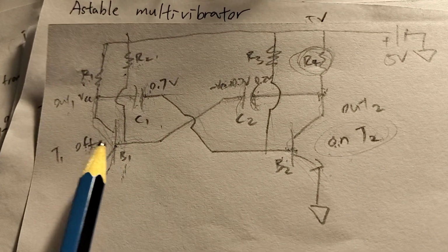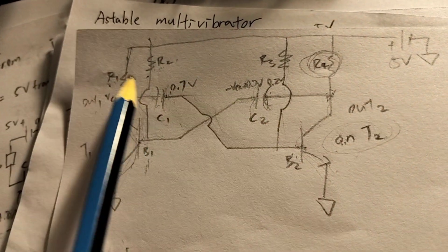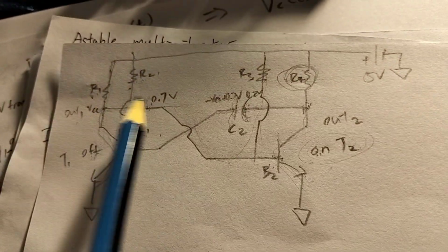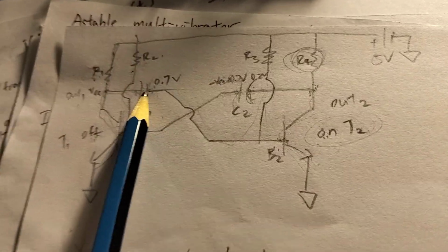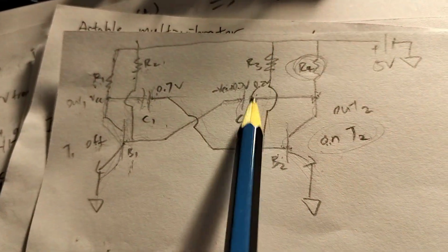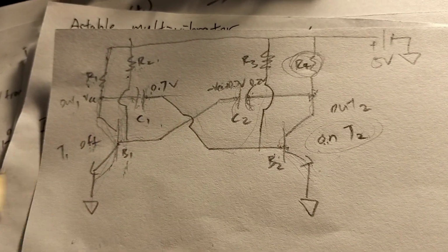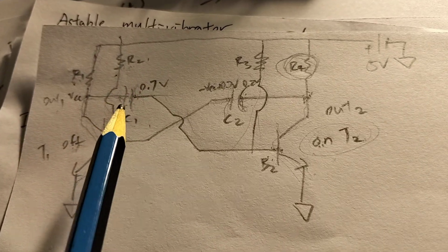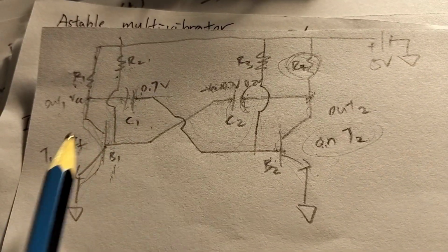And the reason is, I believe, because of this capacitor that's connected to the base resistor on one side and the collector resistor on the other side. If it charges too quickly, which will happen if R1 is too small or R3 is too big, or vice versa, whatever, I don't quite remember, there's a configuration where if the capacitor charges too quickly, it never actually hits cutoff, so it prevents the circuit from hitting cutoff.